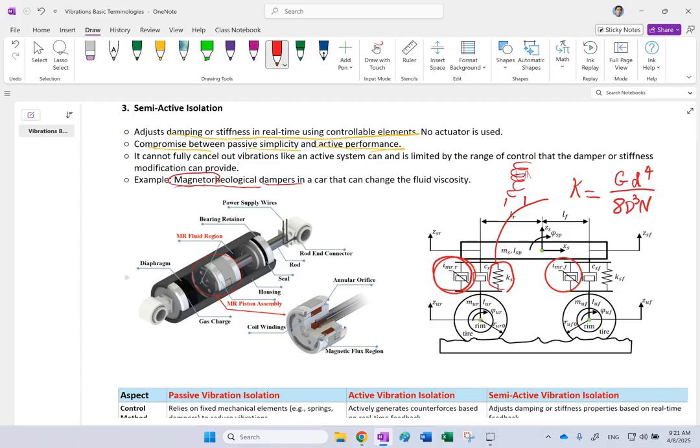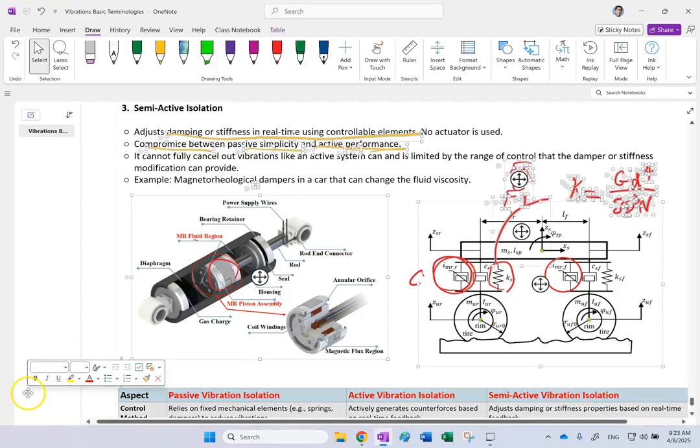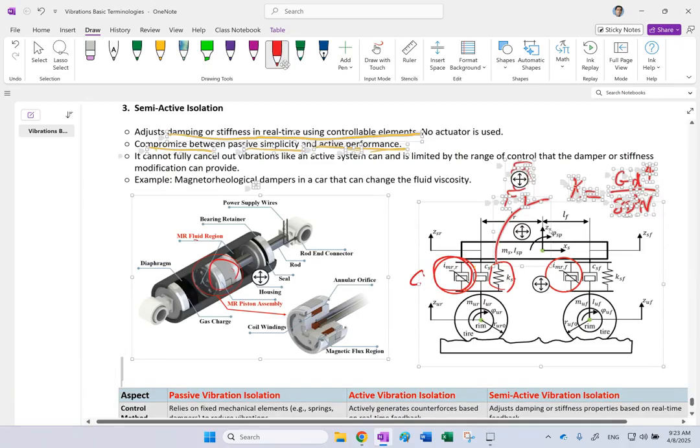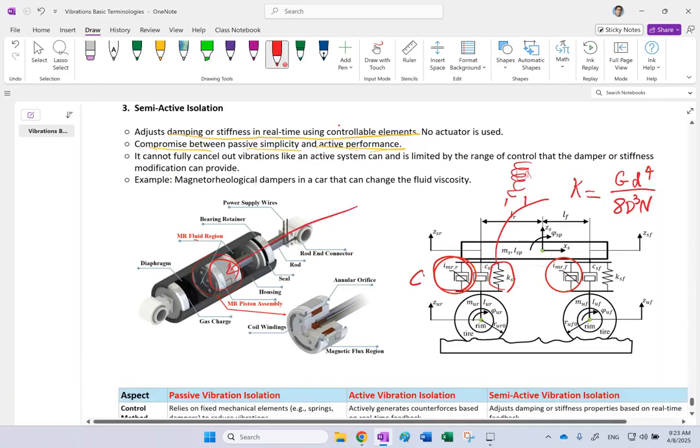Okay, so here you have an MR fluid piston. Inside of them, the viscosity of the fluid depends on the magnetic field. If you apply different magnetic fields, the viscosity, or the C constant, which depends on the viscosity, does change as a function of magnetic field. Now, how does it do it? Well, inside this fluid, inside this oil, there are magnetic particles, okay? So it's not just a pure fluid. Inside of this, there is